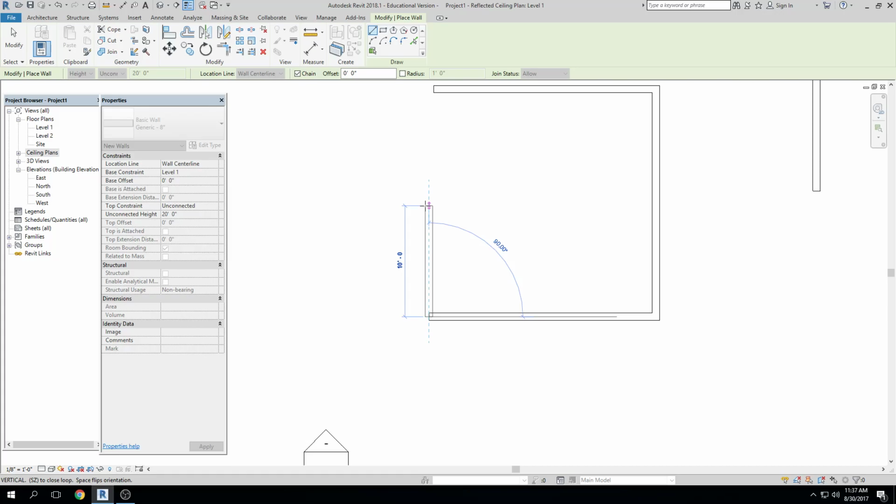We can type something like 20, well, okay, let me say this. If I type 20.5, that means 20.5 feet. So it would be 20 foot 6 inches, right? But I could type 20 space 0.5, and that would be 20 feet and a half inch. Right? So if you're used to using decimals, I do the same thing in AutoCAD.